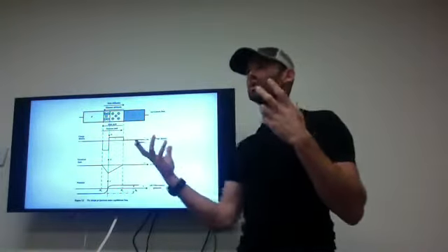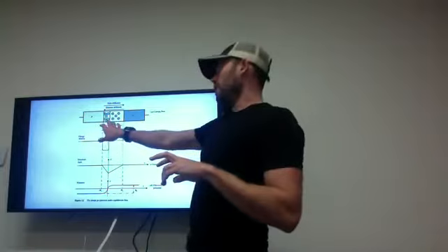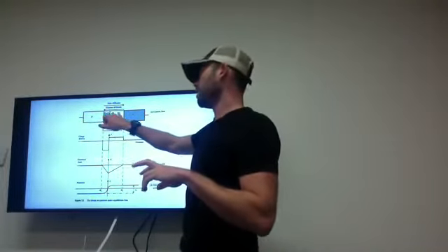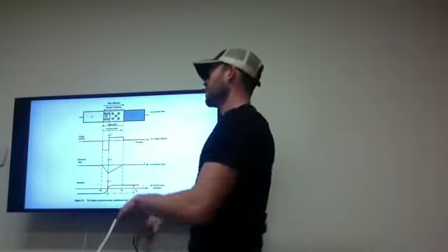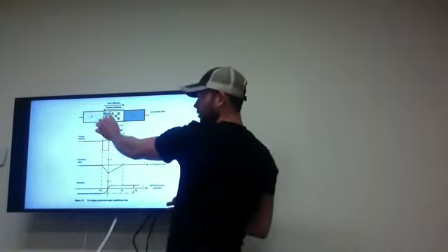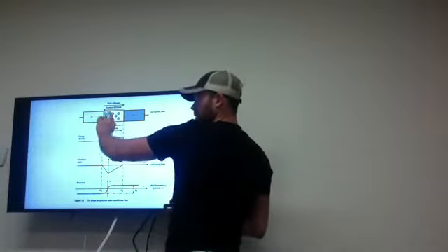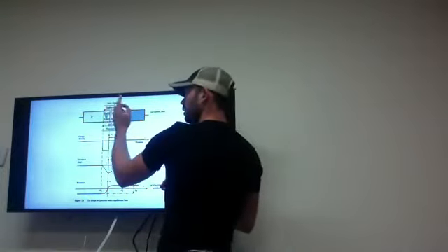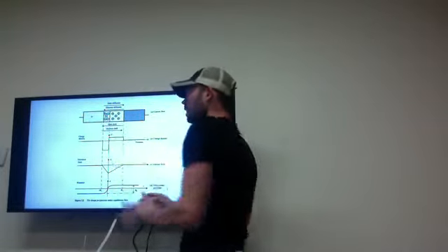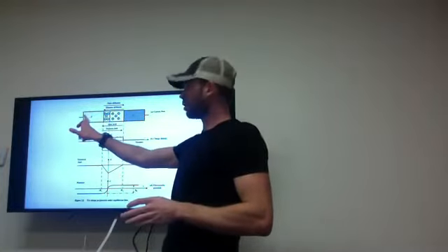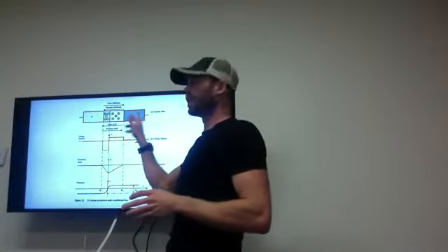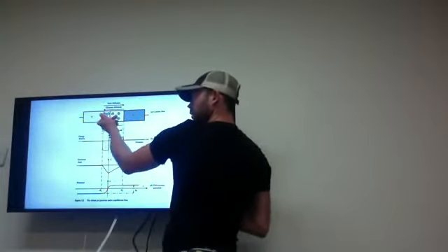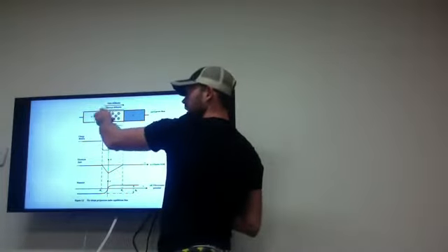The buildup of electrons on the p side and holes on the n side is due to hole and electron diffusion, and this depletion region is built up of oppositely charged particles from what P and N are. So this is actually full of holes, and this is actually full of electrons, but in this region they are attracted, which creates this difference in charge.